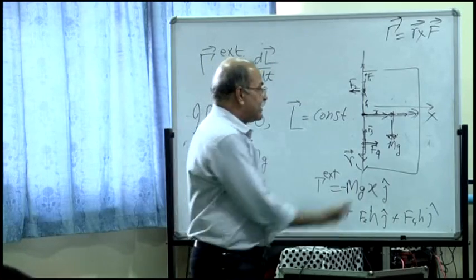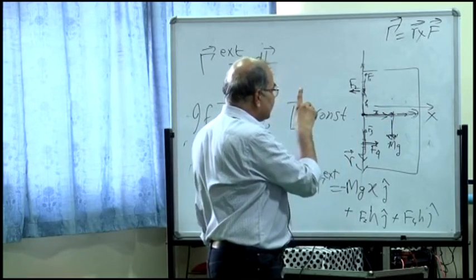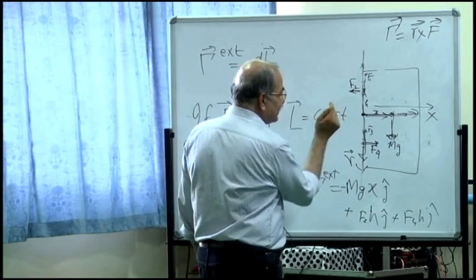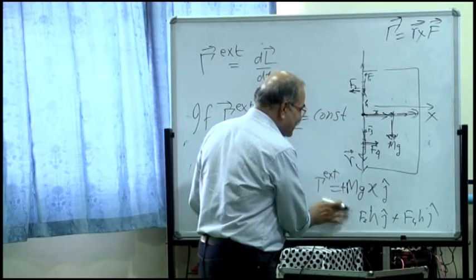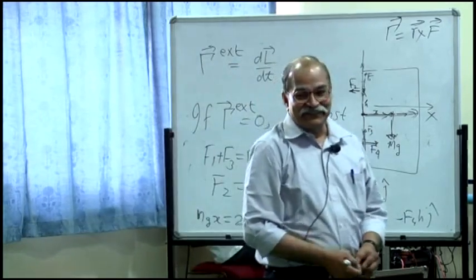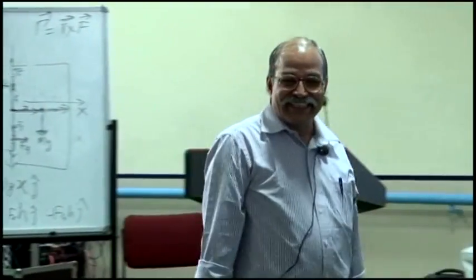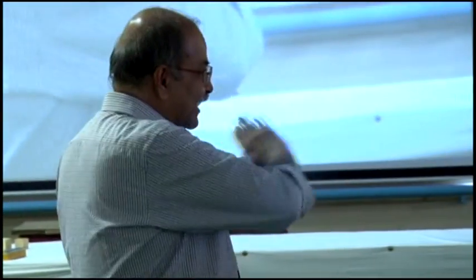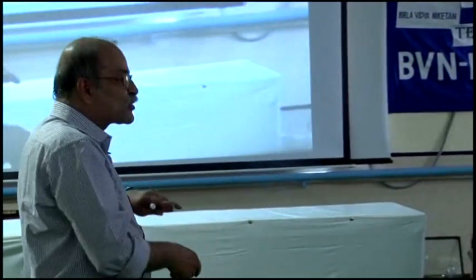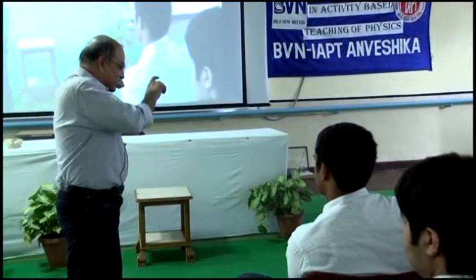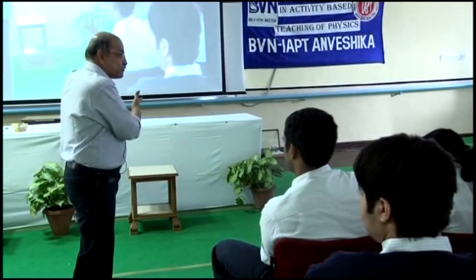Right? So if I take this as Z, X and Y, our Y should be inside, this should be plus and this should be minus. It doesn't make a difference to my final result, but the convention is when you choose XYZ axes, it should be Z, X, and if you cross product, it should go in the Y direction. So your Y direction should be inside. So the torque of mg is inside, so it is in the plus Y direction.